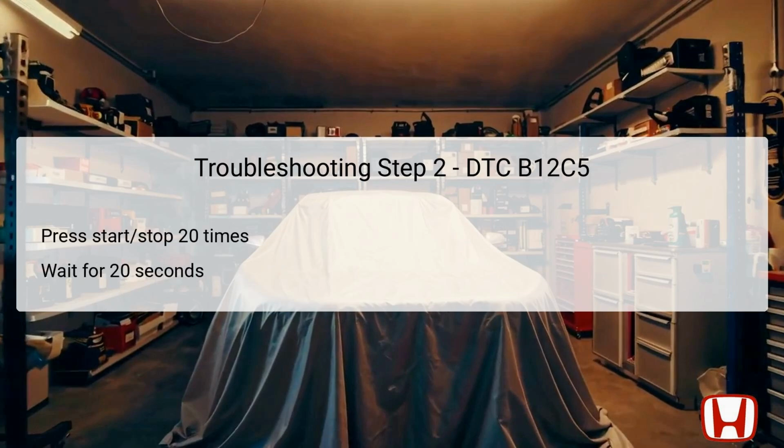In the second step, technicians are instructed to press the engine start-stop button at least 20 times, and then wait for a minimum of 20 seconds before proceeding. This process can help reset any temporary glitches in the system, enabling the unit to recalibrate. The act of pressing the button multiple times may vary the electrical signals sent through the system, potentially revealing intermittent issues that were not present during initial inspections. After the wait, it is crucial to check for any repeating DTCs, which helps to confirm whether the same code, B12C5, persists.